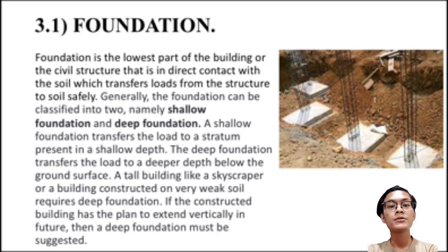Generally, the foundation can be classified into two, namely shallow foundation and deep foundation. A shallow foundation transfers the load to a stratum present at a shallow depth. The deep foundation transfers the load to a deeper depth below the ground surface. A tall building like a skyscraper, or a building constructed on very weak soil, requires a deep foundation. If the constructed building is planned to extend vertically in future, then a deep foundation is suggested.